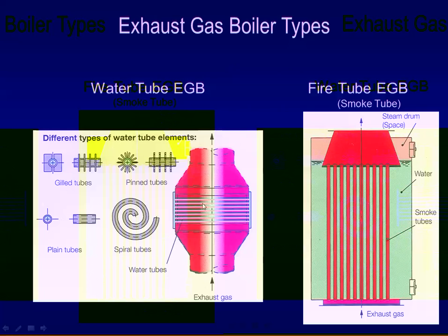If you don't, then that fire can much more readily melt down these tubes, and even more than that, can actually cause the steel to burn, and you'd have a metal fire. And you cannot deal with a metal fire on a ship. So maintain your flow of the circ pump, or boiler water level in the fire tube type, to maintain cooling to the tubes.